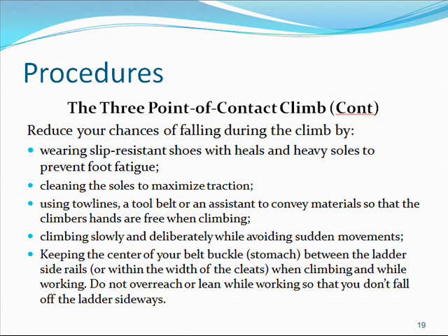Procedures. The 3-point contact climb. Reduce your chances of falling during the climb by wearing slip-resistant shoes with heels and heavy soles to prevent foot fatigue. Clean the soles to maximize traction. Use tow lines, a tool belt, or assistance to convey materials so that the climber's hands are free when climbing. Climb slowly and deliberately while avoiding sudden movements. Keep the center of your belt between the ladder side rails when climbing and while working. Do not overreach or lean while working, so you do not fall off the ladder sideways.